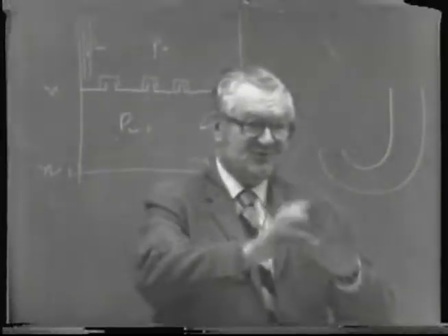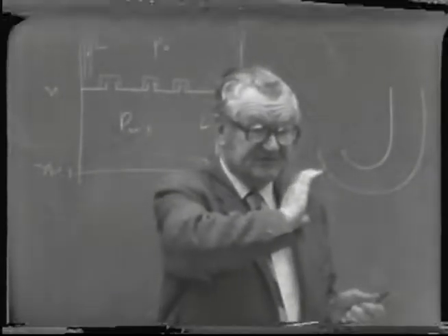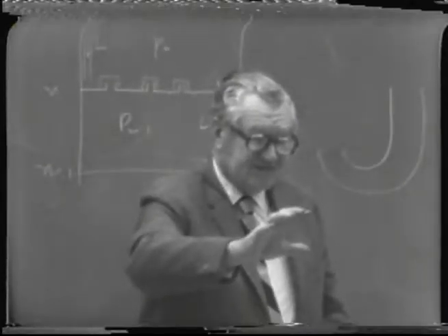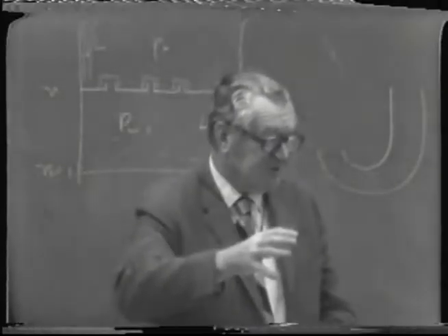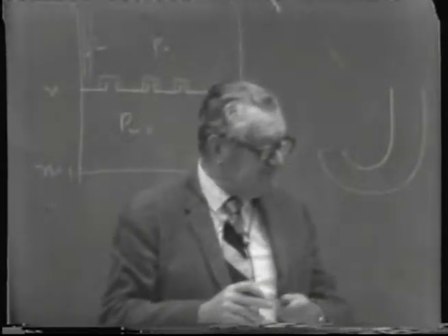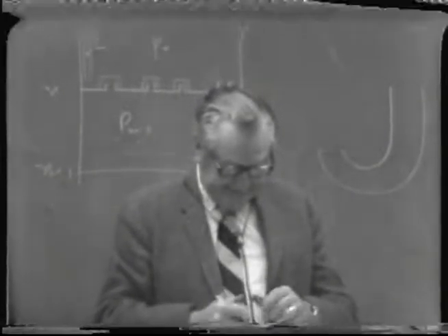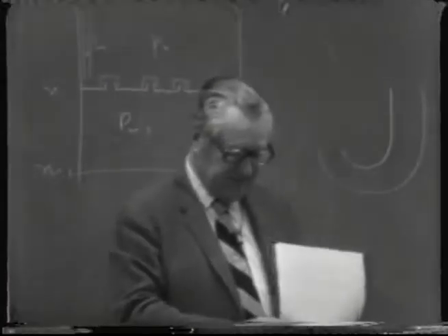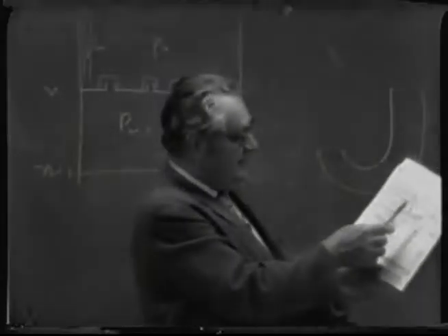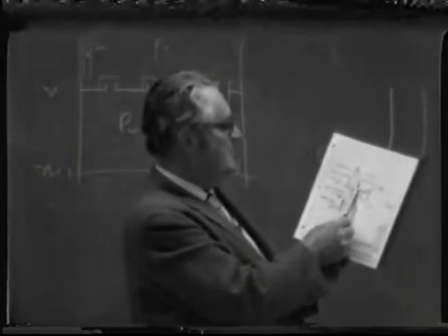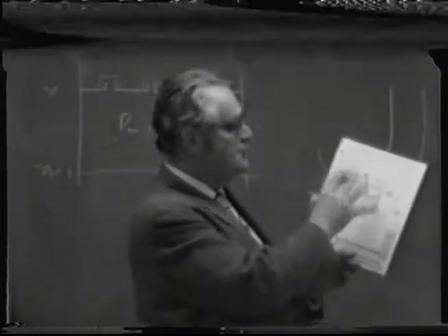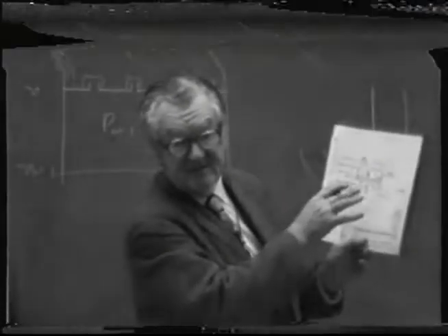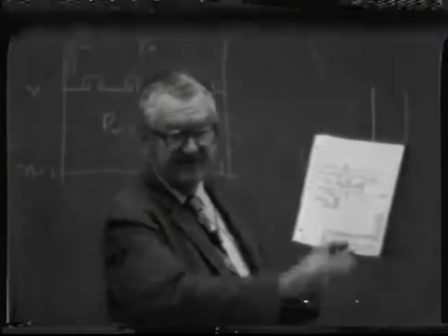When you go through a small orifice, the energy that's necessary to increase the velocity is obtained at the expense of the pressure energy. So you lower the pressure. And if that's in contact with this hot stillage, you can reduce the pressure down to where you get a partial vacuum in a chamber like that by passing the steam energy through it.